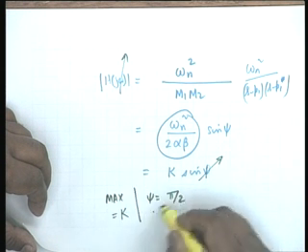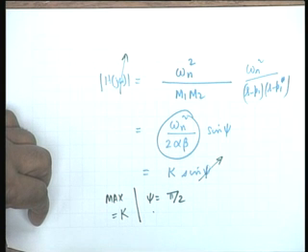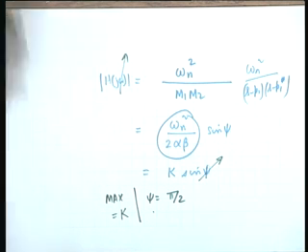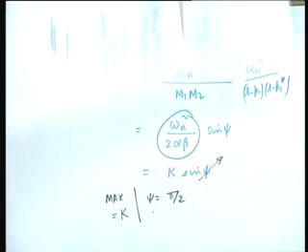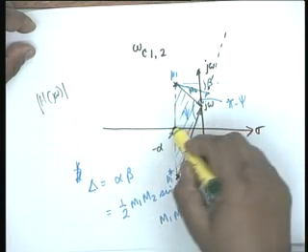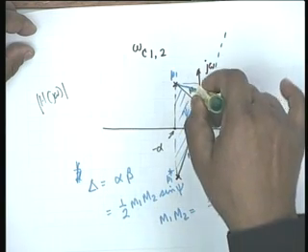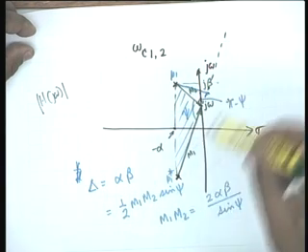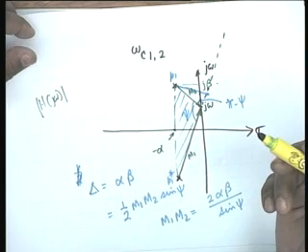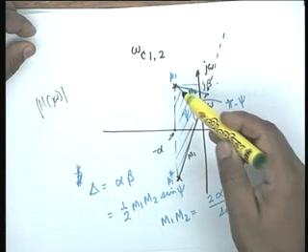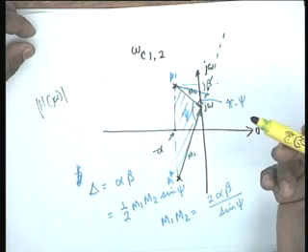And we know where that occurs. We have to draw a circle with this as the center and this as the radius. Wherever it cuts the j omega axis is the frequency omega m. At omega m, the angle subtended between m1 and m2 must be equal to pi by 2. Alright.